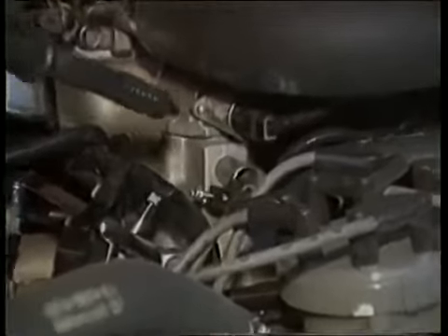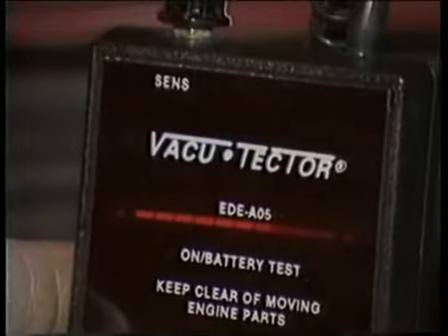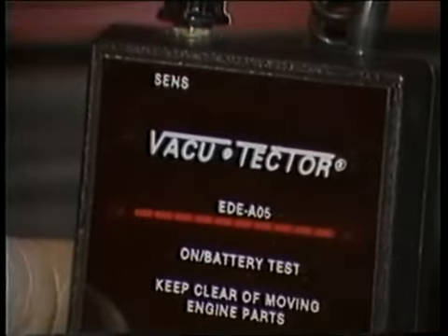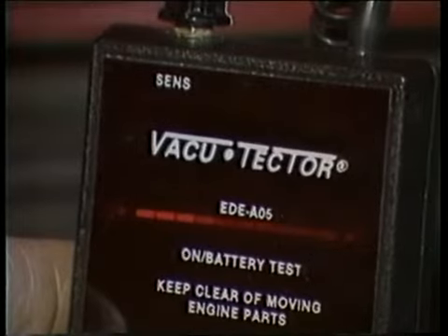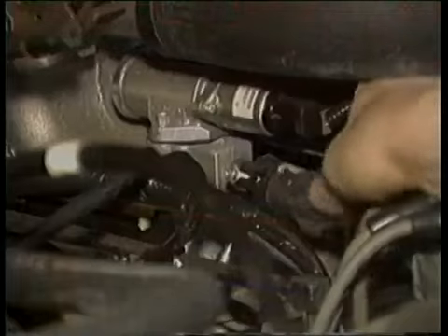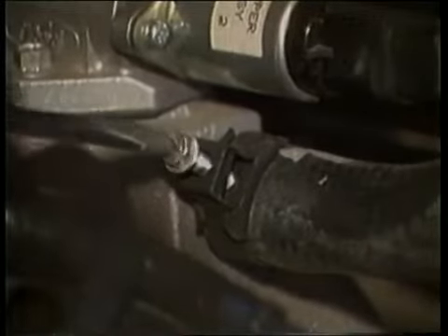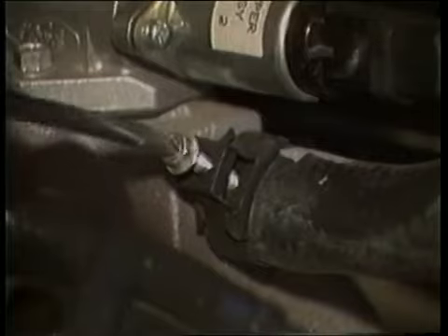Here we have loosened a vacuum hose to show you how the device works. When the probe is moved next to the leak, an audible tone is produced, and an indicator light shows that the vacuum leak is present in that area around the engine. Remember that a vacuum leak will affect the performance of the engine, especially at idle, and you would need to correct the source of the leak. After fixing the problem, recheck for leaks.